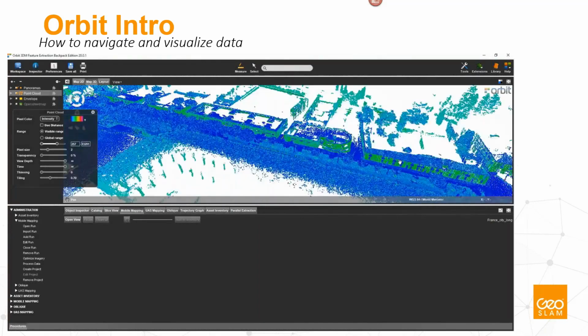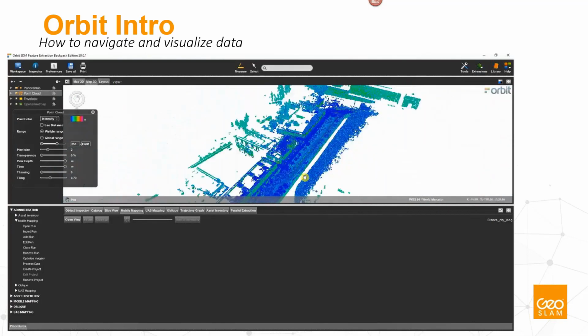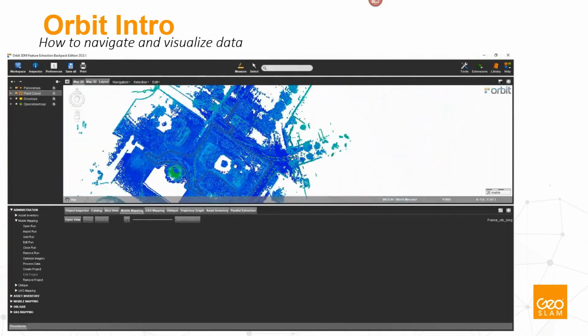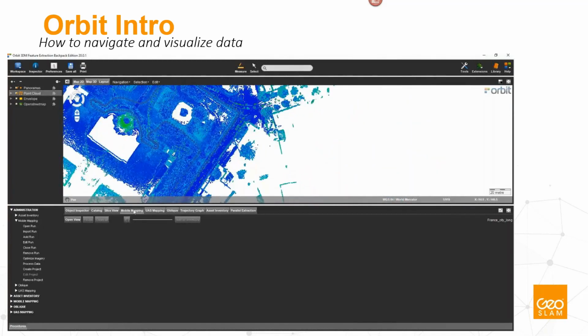So intensity really gives the best view and understanding, but there are, as you saw, other options also. So I would recommend, and I normally keep my point cloud in intensity and just change the scale as required.